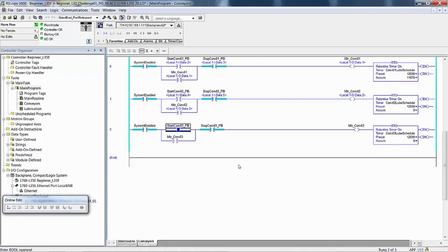Okay, looking here, if I turn on input 2 and input 4, and this one I can't hold on because remember I have that temporary logic that turns it on and back off. But in the manual, it asks you, do the rungs look true? Do these rungs right here look true? This one and this one, 0 and 1. Do they look true? Yes. Is the logic setting the output bits to the on state? Well, does it look like it? No. Are the timers accumulating? No. Just for grins, I see some data table carnage there.